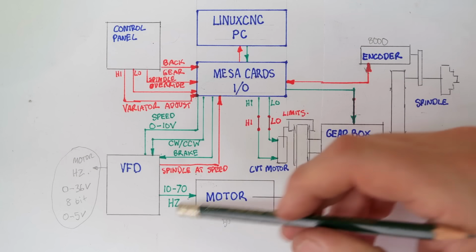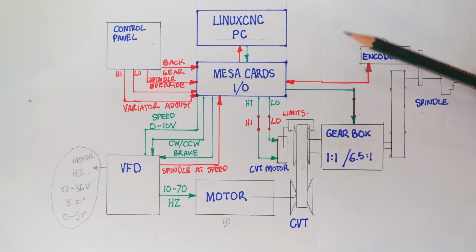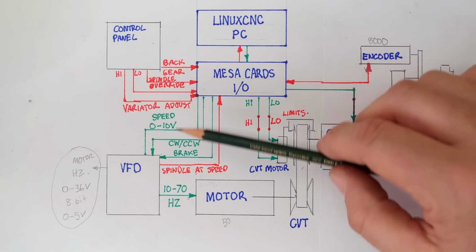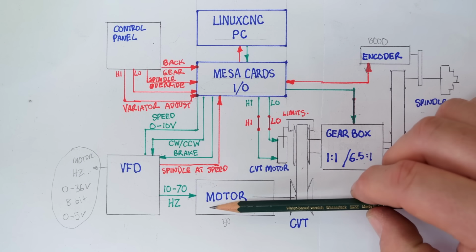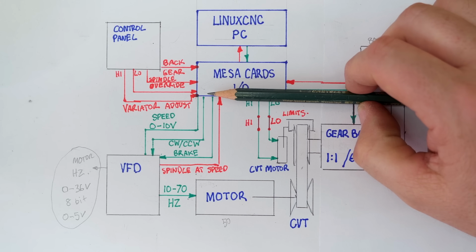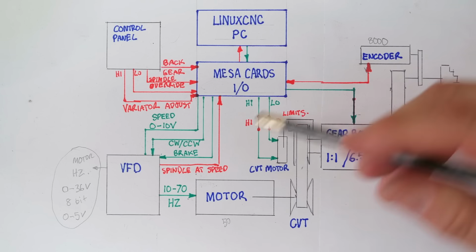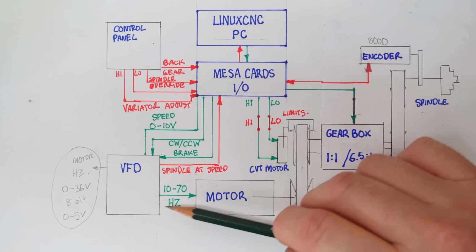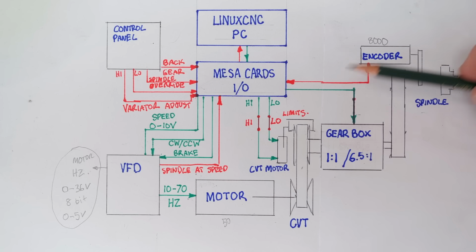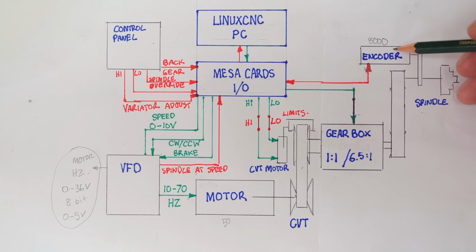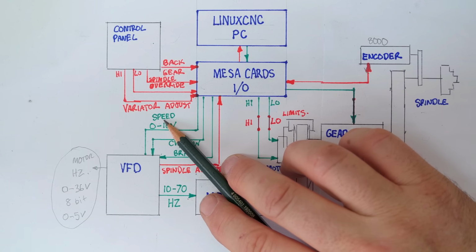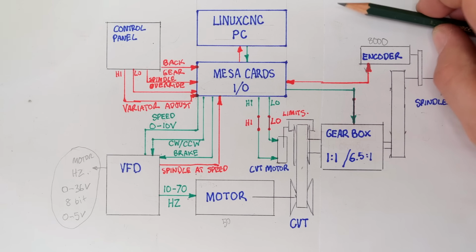The problem I've got is there's no good feedback of motor speed at this stage. So there's really two issues. One, I've got this massive change in inertia in the system between lowest low gears and highest high gears. If I'm going to closed loop control the motor with the VFD, I'm going to need variable PID gain staging to avoid either oscillations at one end or extremely slow performance at the other. To work out which gains I need, I need to know my ratio. How was I calculating ratio? Well, speed out is known, but speed in, the only thing I had was commanded speed. Commanded speed and output speed gives you ratio.